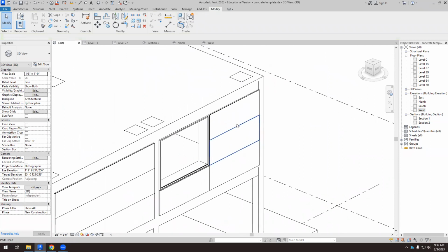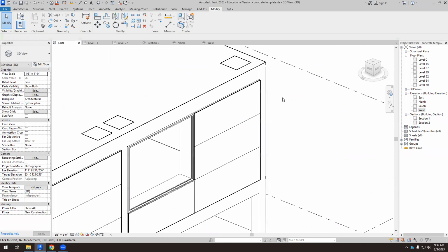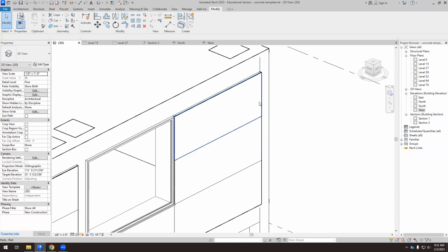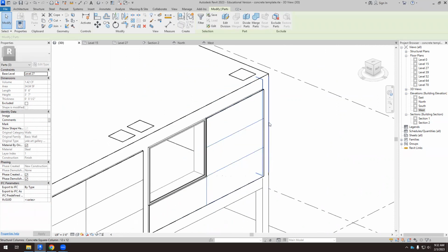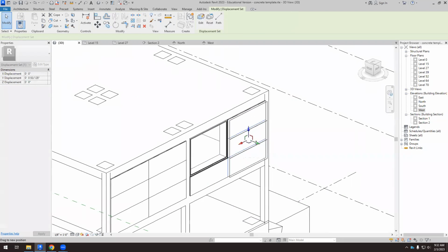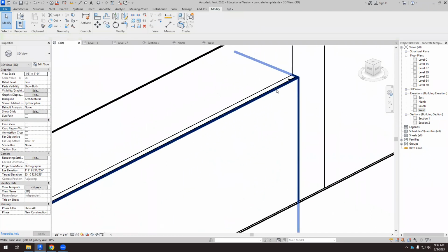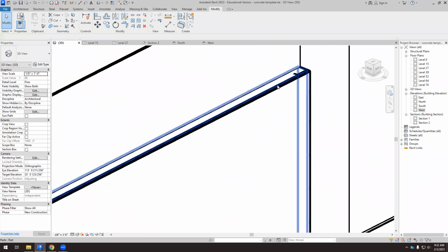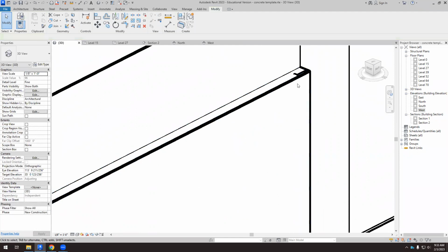And you can tell me, why are we doing this if we don't see that element? Well, that's a wonderful Revit feature, because if we want to see different layers of this envelope, I can always select the parts. I can use these displaced elements, and then I can move it in this direction. What happens with Revit now? Okay, so this is an air layer, but this air layer, it's a solid element, but it's air. So I can always exclude part. So if I exclude part,